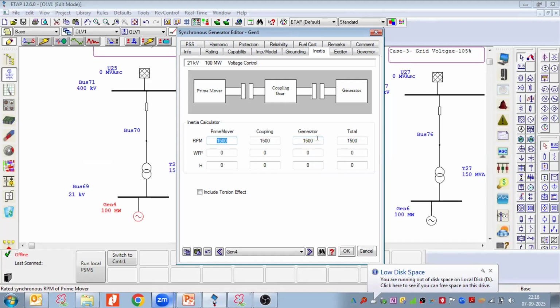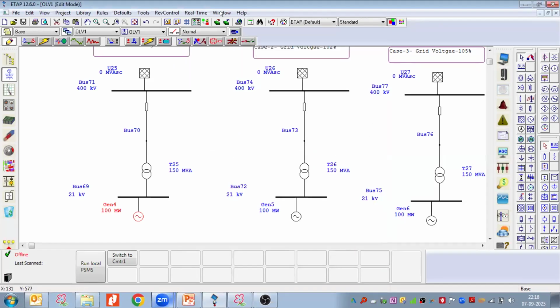Sir, is any data required for harmonics? No, for harmonics also it is not required, but generally we do use harmonic calculation. Suppose we have a generator; for the harmonic calculations, have you entered all those values? Can you please open the harmonic portion? Basically, in ETAP we also calculate the harmonics of equipment, no, sir? Yes, for harmonics we also require generator harmonics, and transformer harmonics.